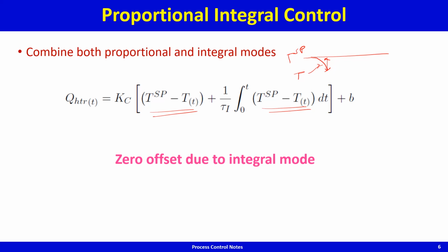So what happens is, if there is a sudden rate of change in temperature in the process variable, even though the error is small and therefore QHTR won't move by much, this term is small, this term is also small. If both terms are small, the change in QHTR will also be small. But cold air has rushed in, temperature is dipping sharply. So what you need to do is make a large correction to QHTR.